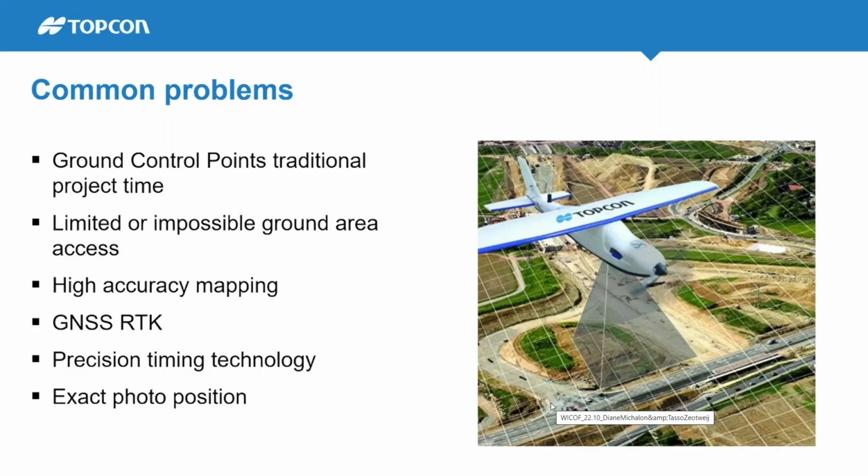What I wanted to tell you about is when you're using traditional means of surveying, you have two problems actually: the difficulty to access some areas and also the exhaustivity of your data set. And that's something that is really, really interesting with UAV. You can access areas that otherwise would have been difficult to access, and you can have a much more exhaustive data set, survey the whole construction site, whereas sometimes you would only have sampled certain areas, for example.